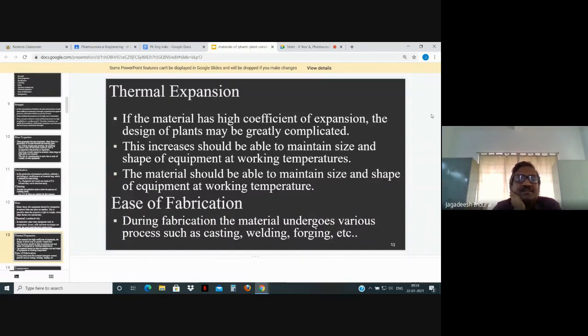The reason is the glass is expanding in the place where it has got hot, but suddenly if any water droplet which is cool falls onto the surface, in that place your material is getting contracted. It is a single continuous round bottom flask, and somewhere one portion is contracting while another is expanding, so it will tend to break.